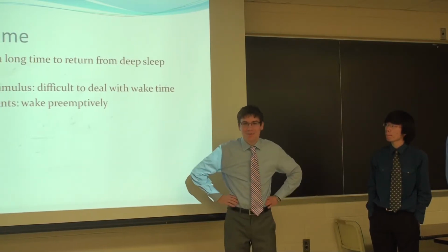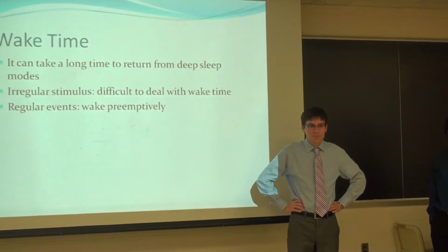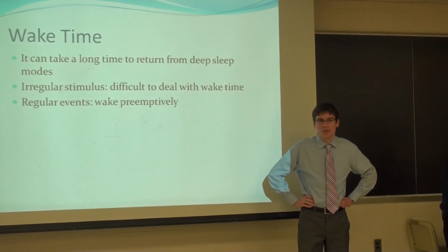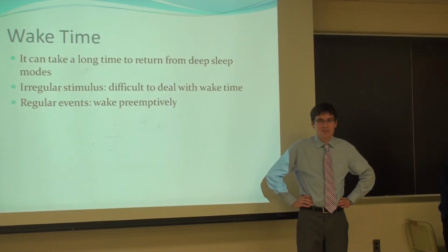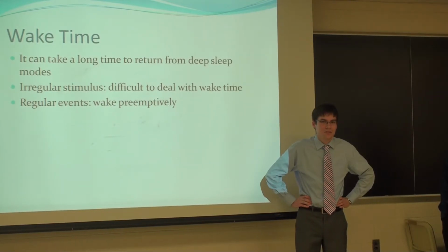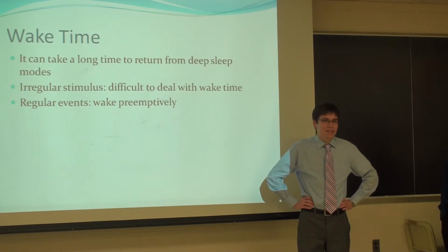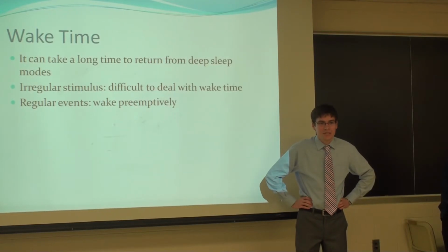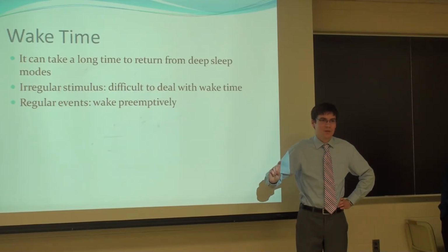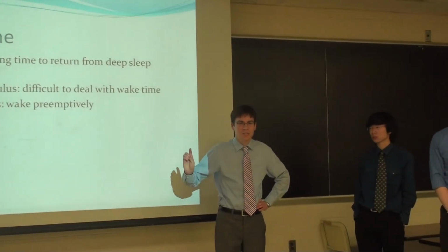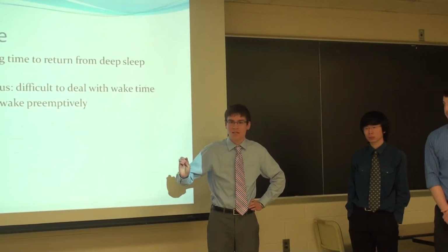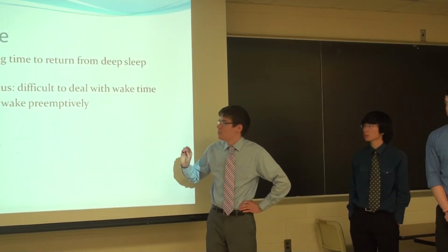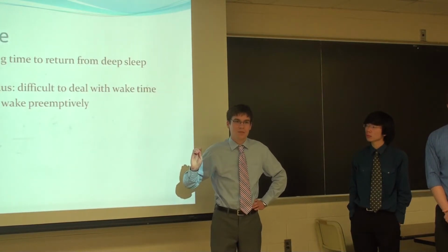So wake time can be particularly hard to deal with when you want to wake up out of a deep sleep mode, especially in embedded systems that need to respond to highly irregular events that can't be predicted. So my example would be an embedded system that's running the anti-lock brakes in a car. You could imagine that a few extra milliseconds between the point where a sensor detects that a tire is slipping to the point where that computer is working to get that car stopped can really be the difference between danger and safety for the occupants of the car. So you have to be careful using sleep modes with irregular events.